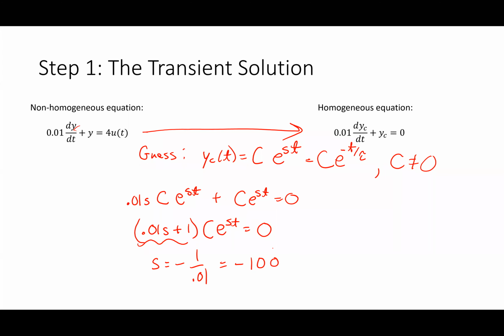My exponential better always have a negative exponent. Why must I always have a negative exponent? Because it needs to eventually disappear. It needs to be shrinking. In order to eventually disappear, that number better be negative. And if it's positive, that means that some capacitor or some inductor somewhere is building up infinite energy, and you're violating all the laws of the universe.